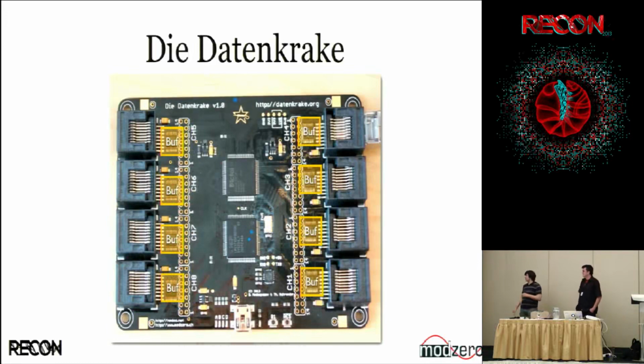I haven't had that much time to try it out, but in general, the FPGA spits out 3.3 volts, but you're not going to blow it just by connecting it to 8 volts, which would be the case if you just directly connected to the I/O. So worst case, you blow one of these buffers, which are easy to replace and fix.